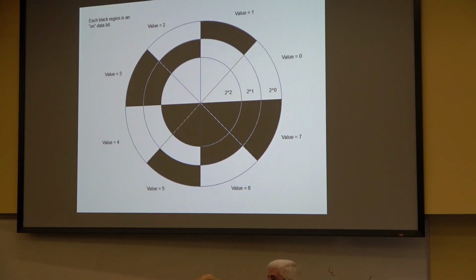And you know, we could do a little machine design on this, and we could actually cut this into a metal disc. We could put 3 photo transistors on there and have 3 data lines coming out. And at any point, we would know which arc segment we're in.